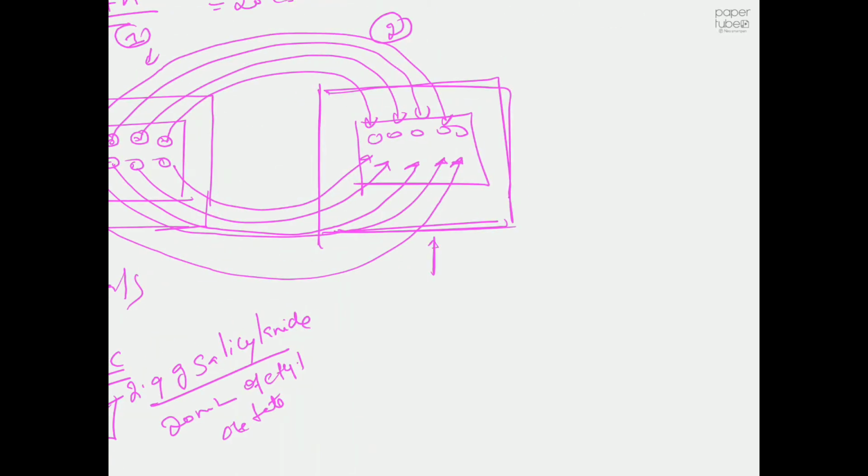The second water bath will be maintained at 15 degrees centigrade, and we are going to estimate the nucleation rate at this temperature. Let's call it the working temperature. Automatically, once your solution drops to 15 degrees centigrade, you will naturally achieve your supersaturation. I already explained how to create a supersaturation in our virtual lab video. So this should create 1.3. That's our supersaturation.